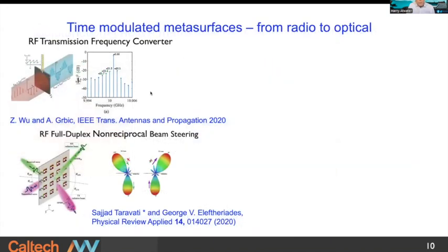So now let's consider going beyond slow, what we call quasi-static reconfiguration, where we reconfigure maybe slowly from one state to another to create a different spatial phase gradient. Note that at RF frequencies, we start with a carrier band and we impress upon it a signal. We can multiplex multiple signals on the same carrier band via time modulation of the RF transmission.